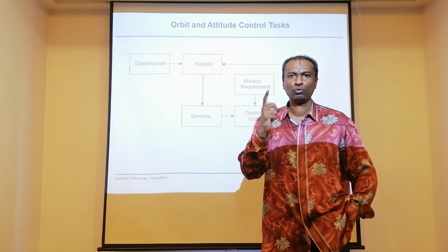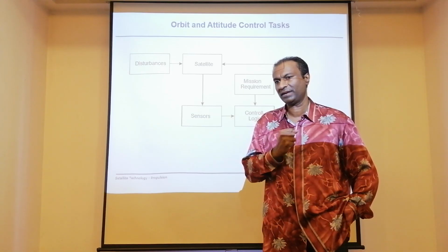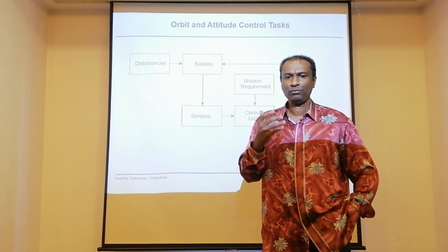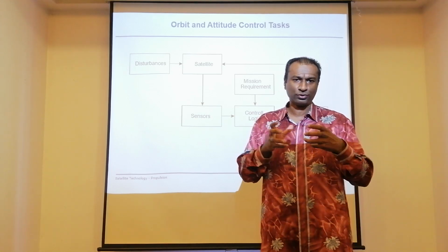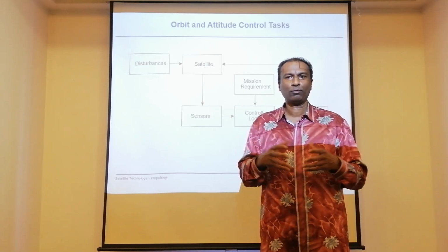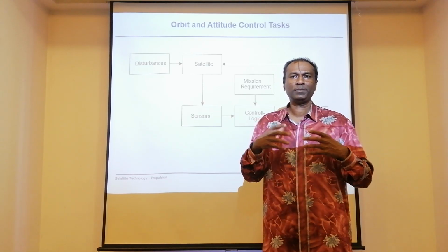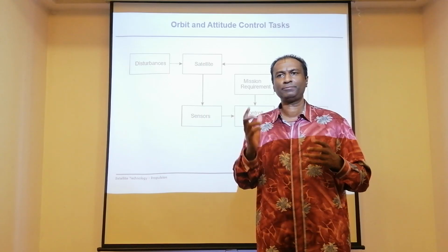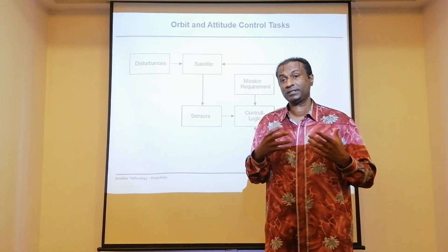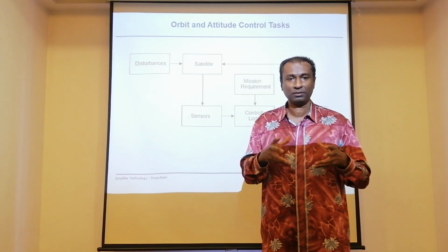These are the two motions we always have to talk about when we want to fly a satellite. In chapter 3, we treated the rotational motion with devices such as the reaction wheel, momentum wheel, control moment gyro, even the spin stabilized technique.